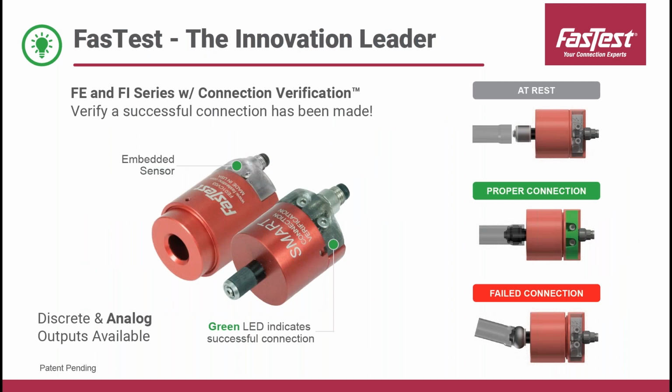So our solution to that problem and those problems is called connection verification. We've embedded a sensor in our FE and FI devices to verify that a successful connection has been made. This has been installed multiple places throughout the U.S. and Mexico. We've seen it used anywhere from medical device manufacturers doing some component testing all the way up to tier 1 engine testing, used for some functional testing and hot run testing of engines. We have discrete and analog outputs available for this sensor, and today we're focusing on the analog.